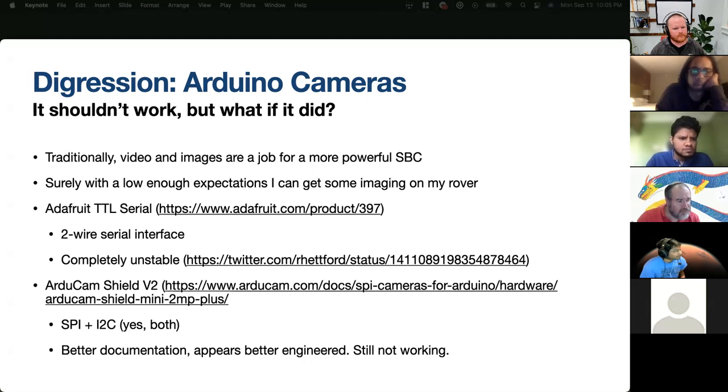I'm thinking that the video stream is supposed to go relatively uninterrupted, and that's why they don't want to mix it with control. They want you to be able to very reliably, every microsecond, get a packet. And I'm wondering if that's what's causing your noise problems, that you have a timing problem getting the data, suddenly you're doing something else, and when you come back, you're off by 2 bits.